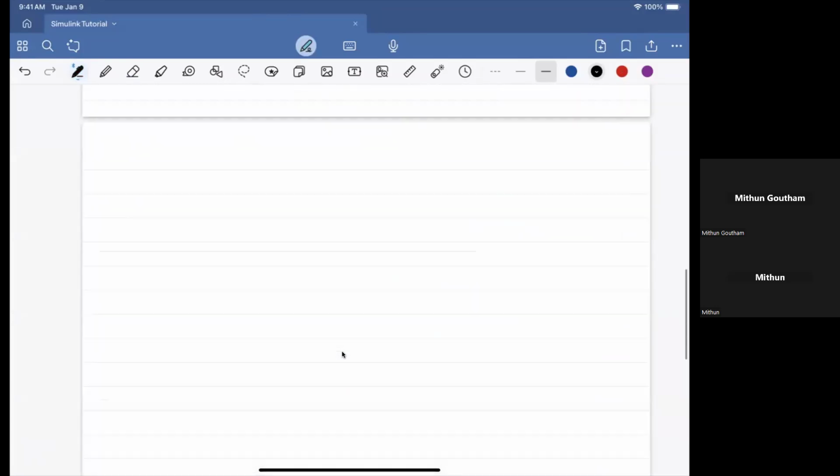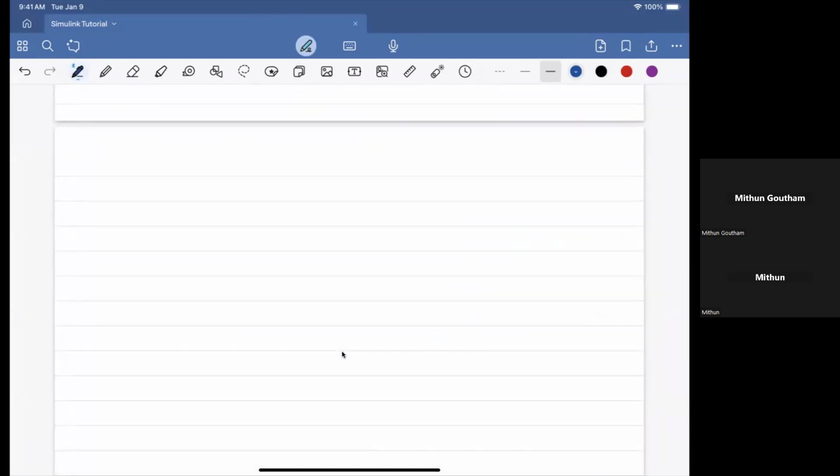trust me when I tell you that one of the equations of motion was m1 x1 double dot. I'm not going to assign values. So m1 x1 double dot plus c1 x1 dot plus k1 x1 minus c1 x2 dot is equal to 0 is one equation.